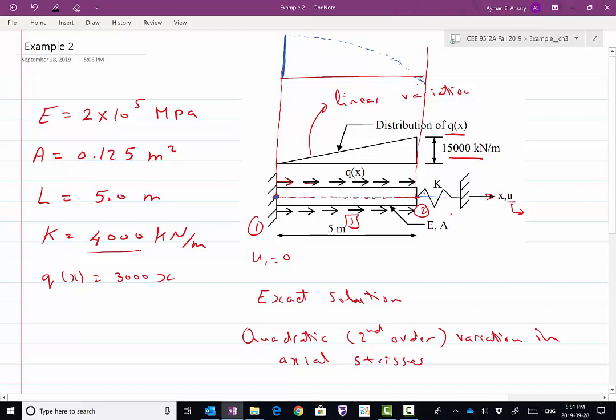So this spring will apply compression force here because the bar is trying to deform and the spring is preventing it, so you'll end up with very small, or whatever the value we don't know yet, so you'll have tensile stresses along the length of the bar, but close to the end of the bar you'll end up with compressive stresses. So we'll see what the values coming from SAP are, but we have a kind of initial prediction of what we are expecting as the outcome from SAP.